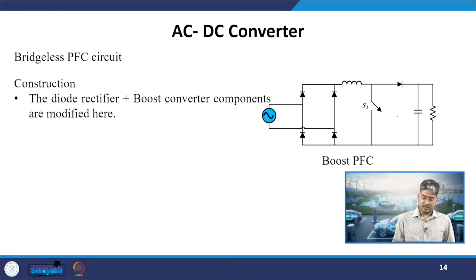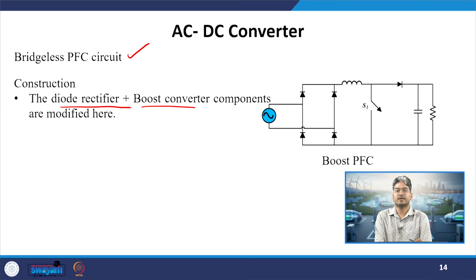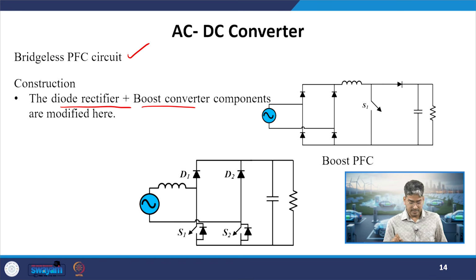Yes. So, one of the other solutions is your bridgeless PFC. So, in this solution what will be done? Now, we will try to combine this diode bridge rectifier with the boost converter, and try to design a solution which will require minimum number of components, and it will have better efficiency compared to our Boost PFC, where the number of devices in the path for any given time period will be less than 3. So, here this is the circuit diagram of bridgeless PFC.